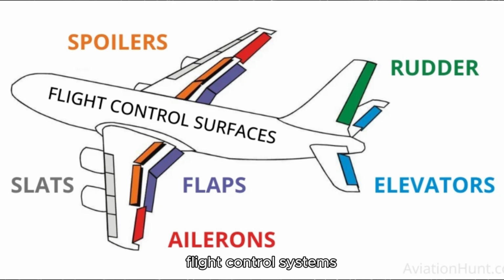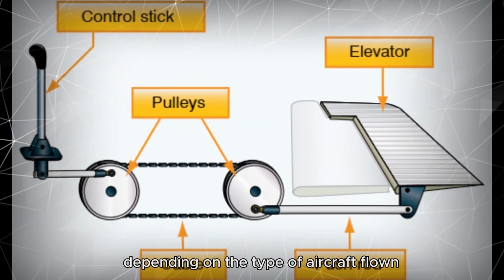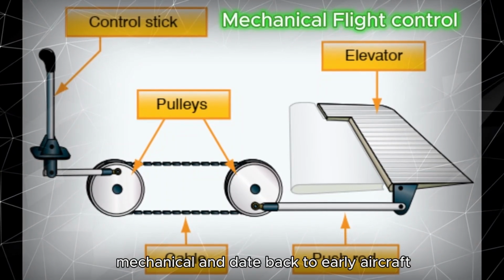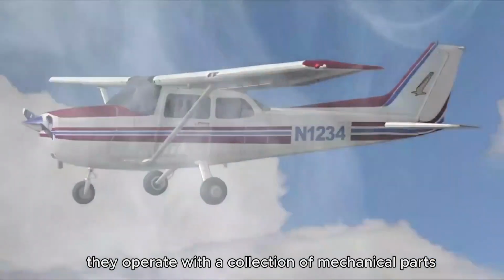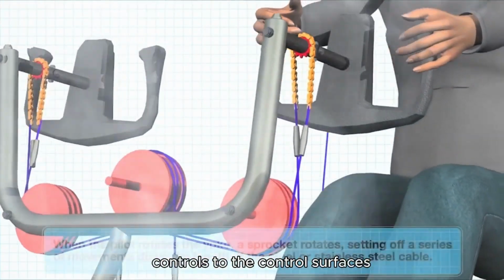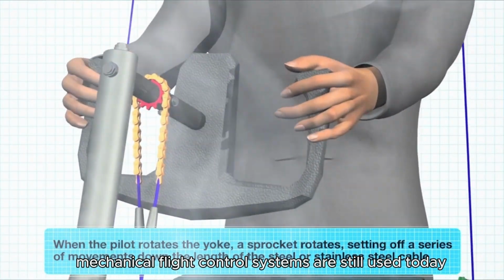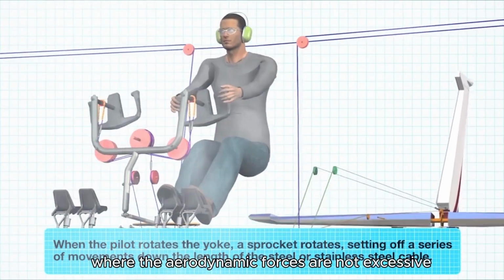Flight control systems and characteristics can vary greatly depending on the type of aircraft flown. The most basic flight control system designs are mechanical and date back to early aircraft. They operate with a collection of mechanical parts, such as rods, cables, pulleys, and sometimes chains to transmit the forces of the flight deck controls to the control surfaces. Mechanical flight control systems are still used today in small general and sport category aircraft where the aerodynamic forces are